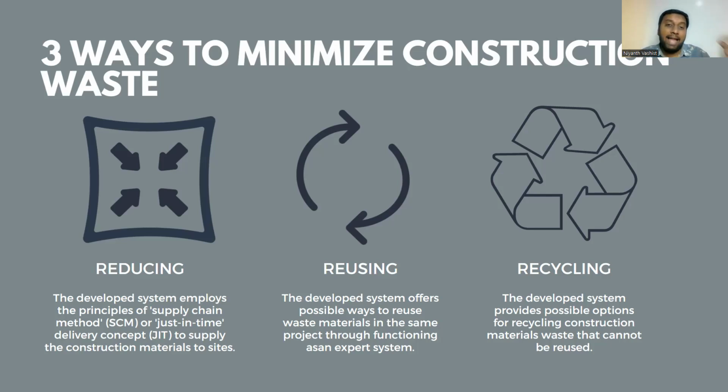But if you don't plan the purchase of materials well enough, sometimes the materials will come way early, will wait 10 days, 15 days in the store, will deteriorate in quality, and then will be used. Hence, it might be wasted also. Especially things like cement or soil, make sure that it is not too early than your construction, because even a small amount of moisture will kill its setting time.